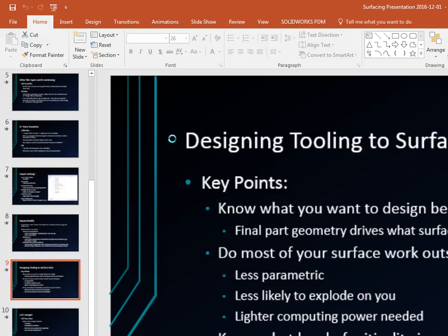So I've got these two surfaces in there, and you can see I actually extended out the outside boundary of those as well, which was kind of a mess in a couple areas, but it doesn't really matter that it extended further before I made the IGES for this one. So I just did extend surface on all the outer edges of that.